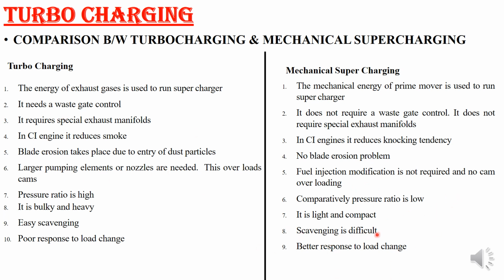Scavenging is difficult, whereas in a turbocharger scavenging is very good, and a better response can be obtained due to load change. So these are the comparisons between turbocharging and supercharging. Next we'll go for the intercooler and turbocharger lag.